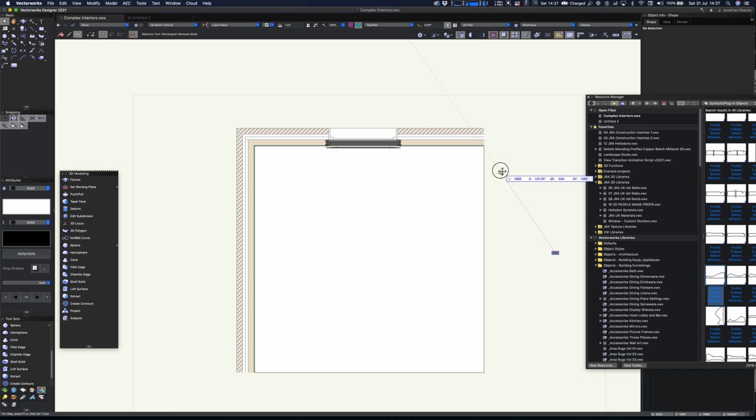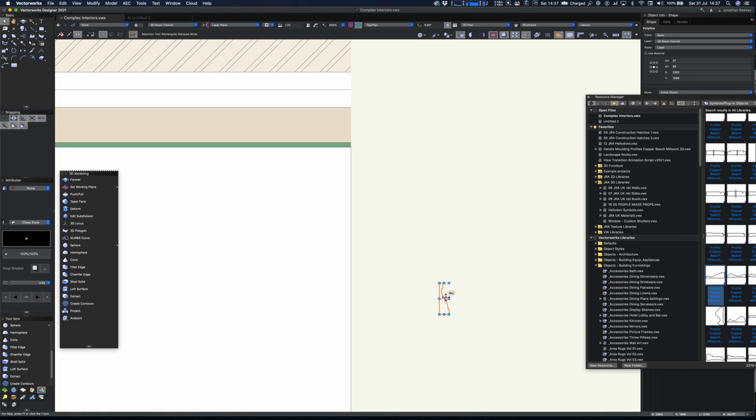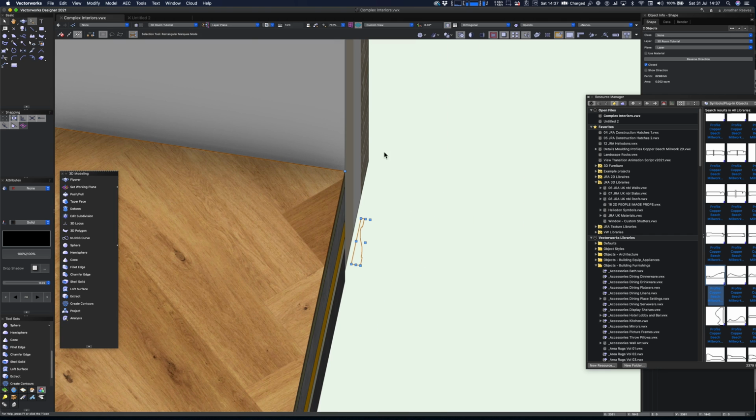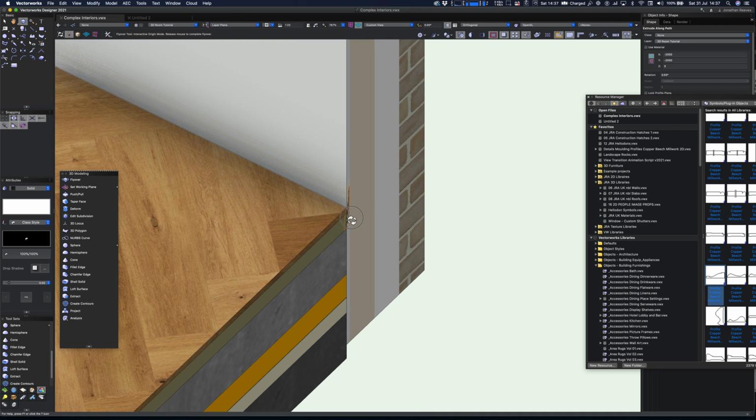I do notice they come in a bit small sometimes, so let's rotate it round first. And let's see if we can scale it. That's looking good. Yeah, we can. Some of them you can scale by dragging. Others you want to scale using the Scale Objects tool. Okay, good. So we just need to select them once again, go to Extrude along a path, click OK, and see how it goes. There we go. Got it wrong again. But it's no problem.